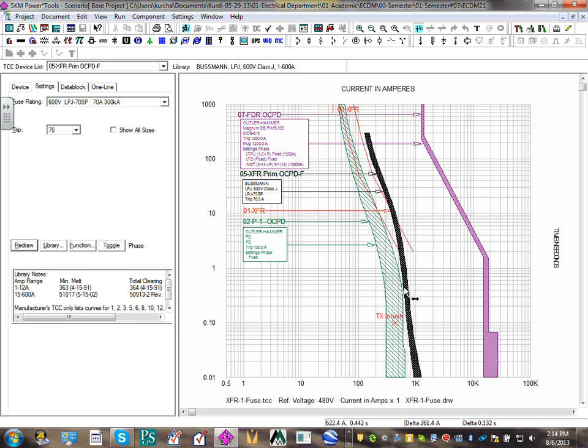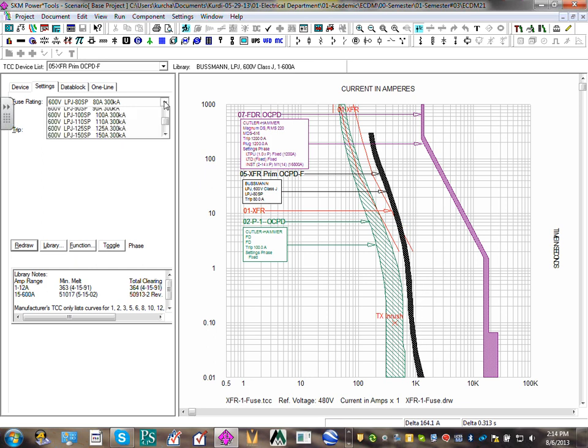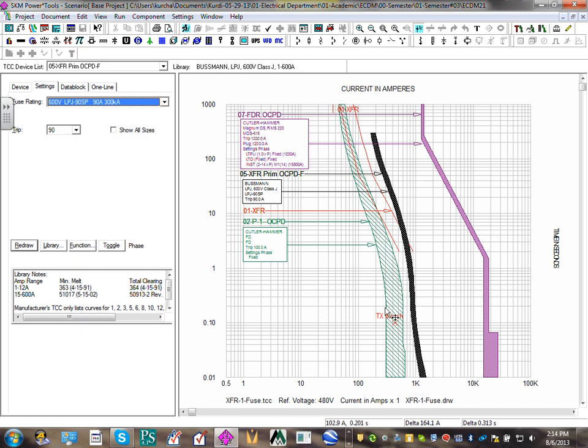But typically I like to size it, like we said, at 90, because I already have enough margin on it. So where would they go? Here you go, 90, 80, and you can go from here to my 90. So here's my 90. I'm clearing, obviously, and protecting my transformer between the primary and the secondary.